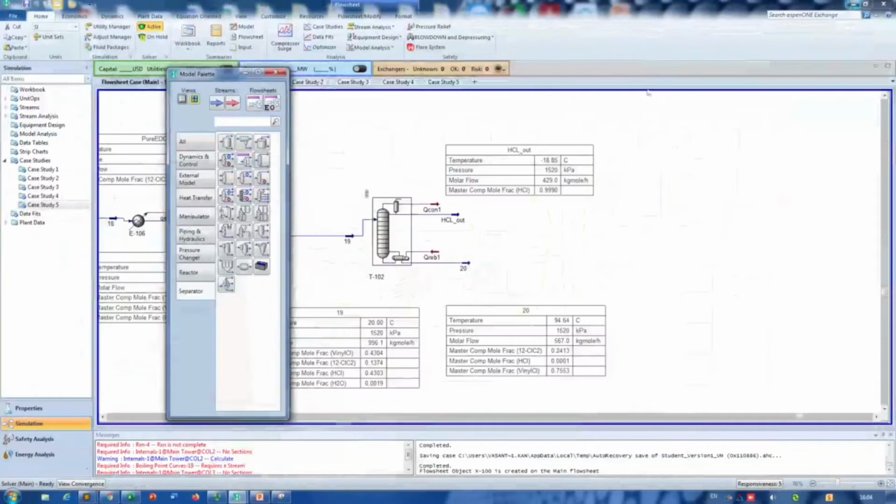So why are we going to do that? Just to make sure we are in the economical distillation zone, so that our condenser pressure should be okay. It was not bad in fact, but let's try to decrease the condenser pressure to nearly 25 to 49. Let's give it a try.